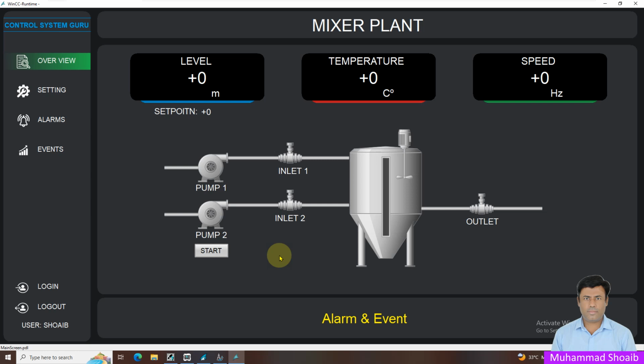When we configure a short pulse from SCADA to PLC, the pulse duration is very short, so there is a possibility that the pulse is missed and the PLC, RTU or DCS system does not receive it. Then our logic and the other process will not execute. The operator assumes he already sent the command, but the RTU or PLC did not receive it.